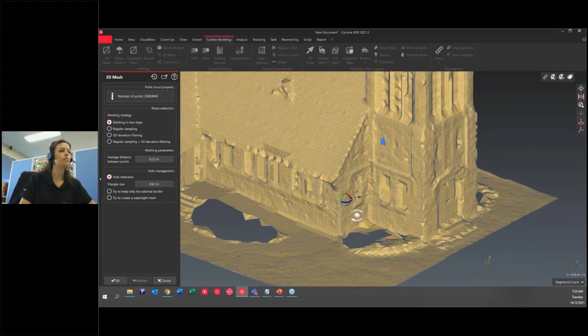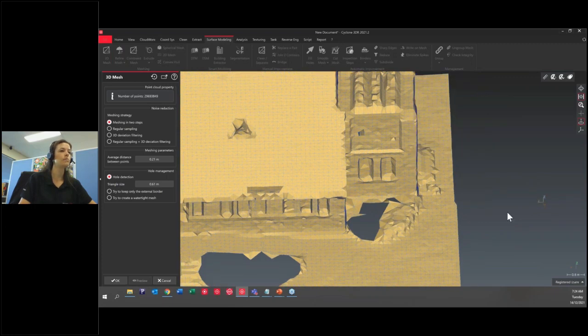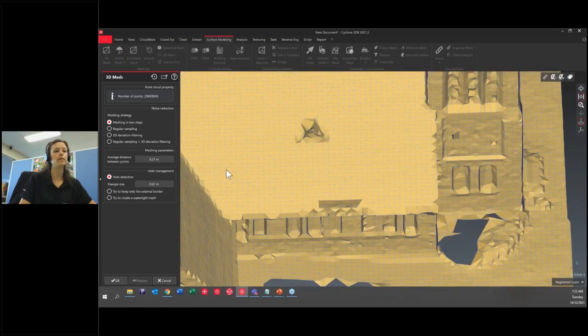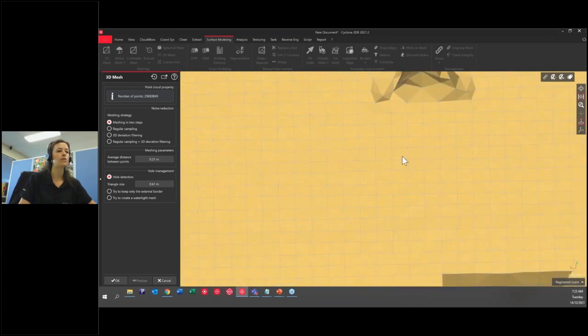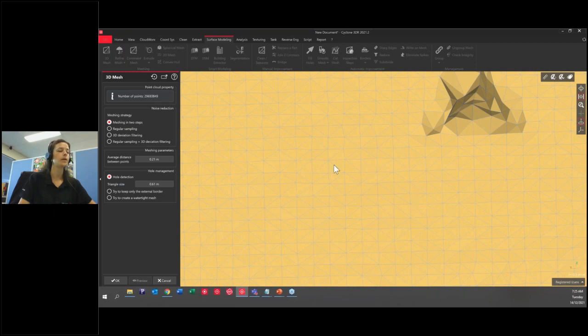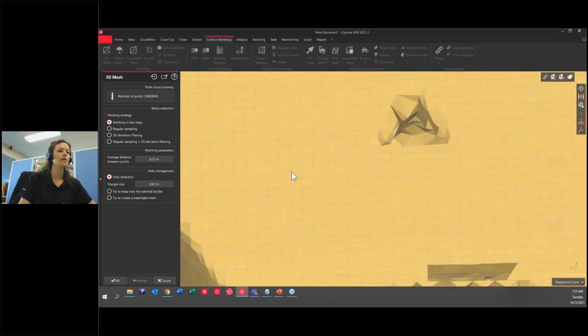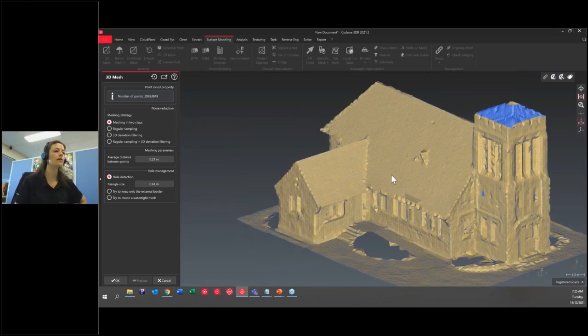What you can see, hopefully, and if I align on X and Y, you can see that our mesh is extremely regular. So it's regular in X, Y, and Z. And so the size of the triangles is approximately 200 millimeters, which is the value we've got here. And you can see that thanks to the little scale at the bottom. If you put it on top like that, that's what you see. So what's happening here is that we just have a regular mesh all over the area.